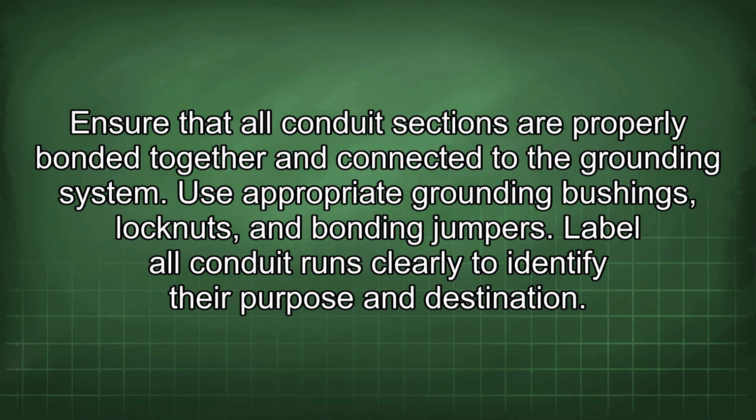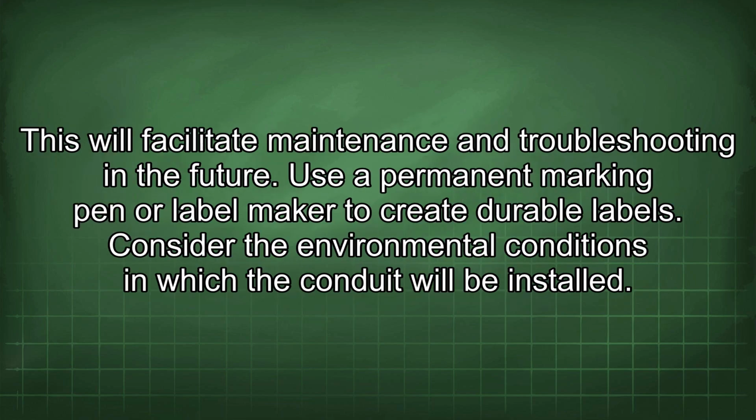Label all conduit runs clearly to identify their purpose and destination. This will facilitate maintenance and troubleshooting in the future. Use a permanent marking pen or label maker to create durable labels.